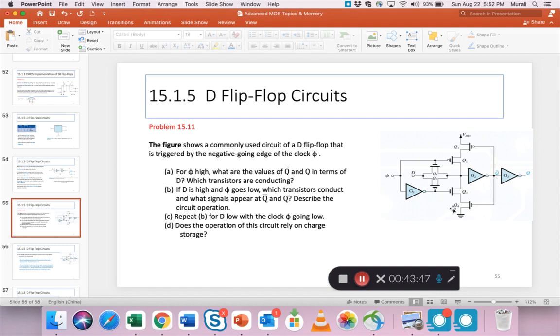So it's a different kind of configuration. And the cross linkage, the cross connections that we normally see in latches, happens through this pair of transistors, Q1 and Q2, and this pair of transistors, Q3 and Q4. So connecting the output back to the inputs of the other gate happens through these pairs of transistors.